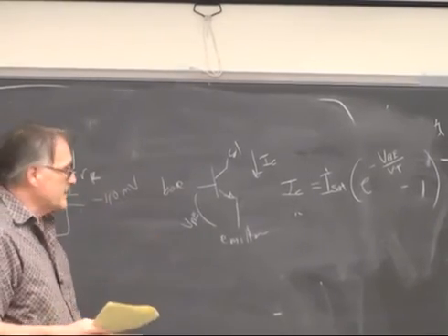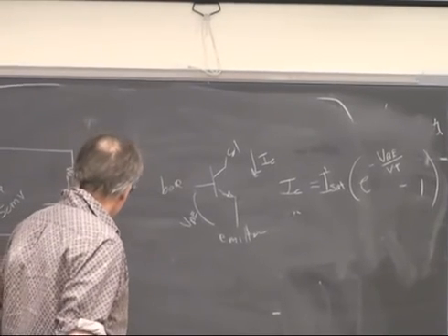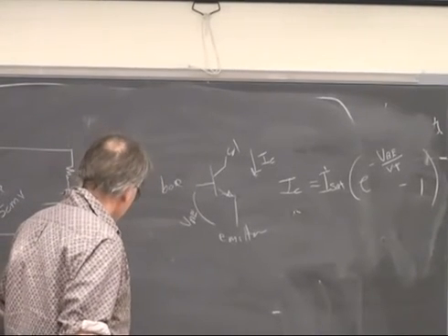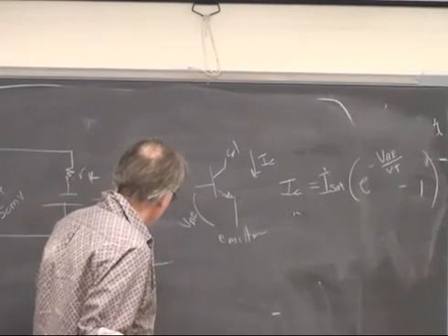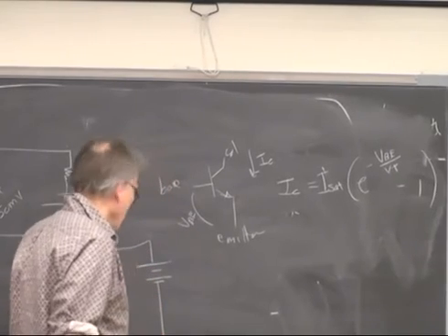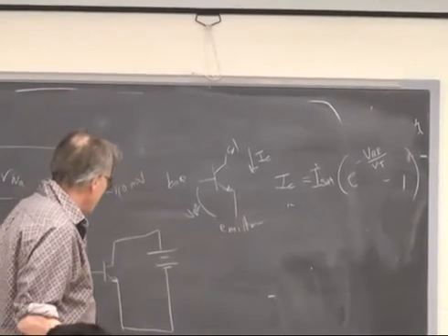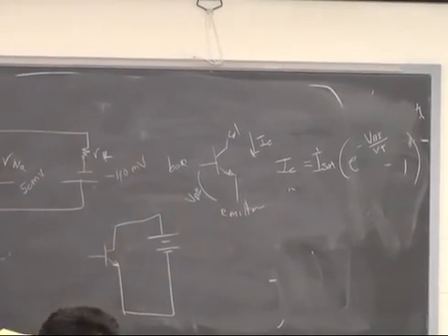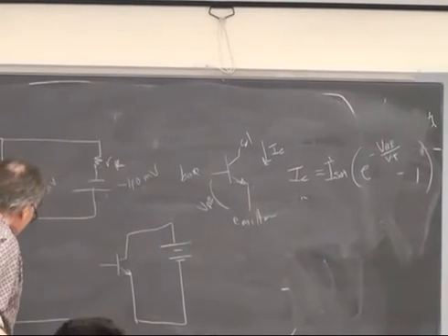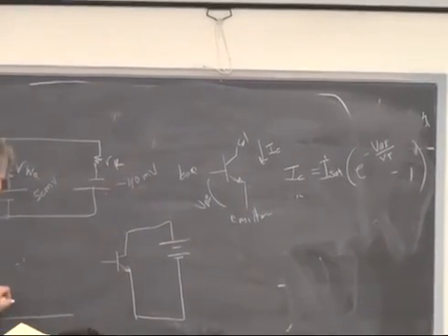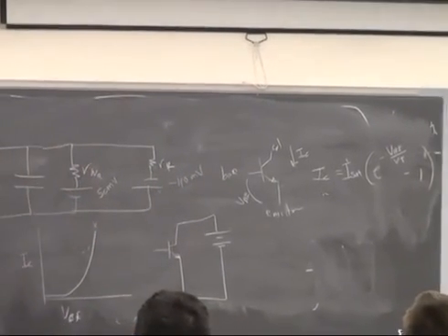And it's pretty easy to see that if you were to then make a circuit that looks like this, this is a bad thing to do. You don't ever actually build this. But if you did build it and you plotted now IC versus VBE, you'd see a nice exponential increase until the smoke comes out of the transistor and it disappears.